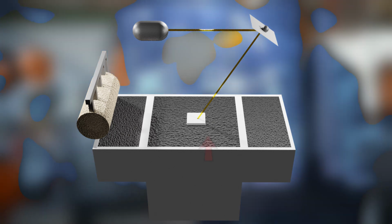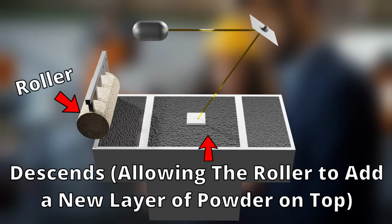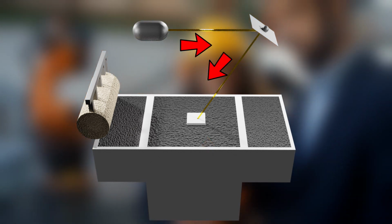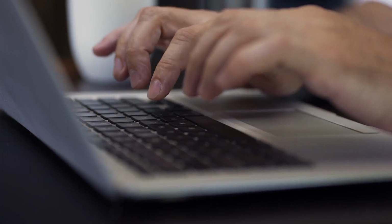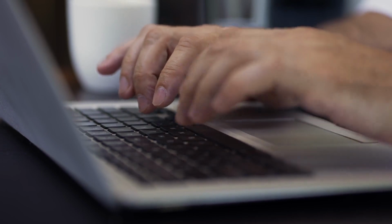the build platform. The build platform then descends by a small amount, and another layer of powder is spread on top. The laser then fuses the particles again, following the pattern of the next layer. This process is repeated layer by layer until the entire object is completed.